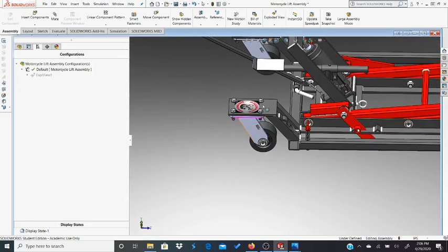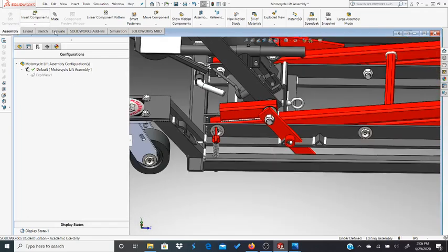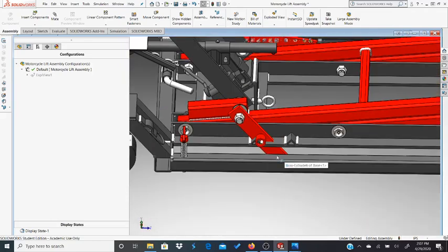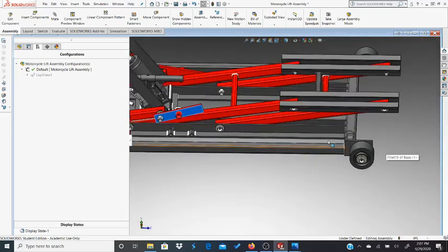Also, you're probably wondering this whole time, what are these little things? You can't see it, I took it off of my toolbar. These are weld simulations. It's the visual of a weld. So I put 3/16 welds on every single piece that would have been prefabricated if you were to do just the assembly, if you're not creating each piece from individual angle iron and tube steel.